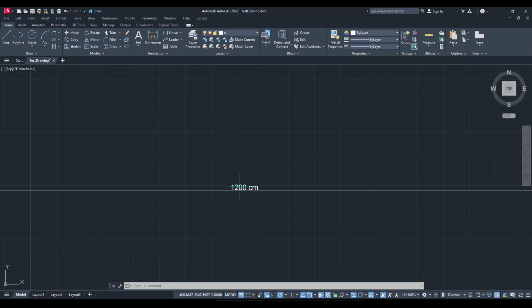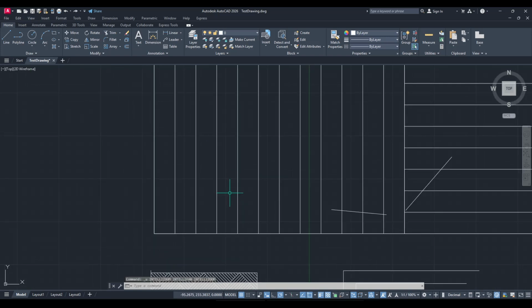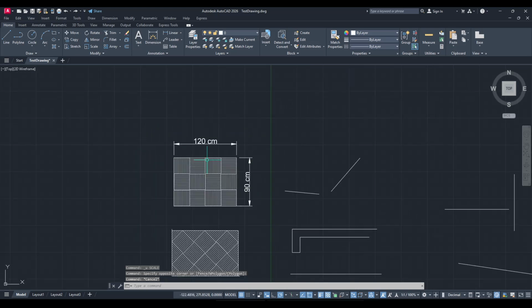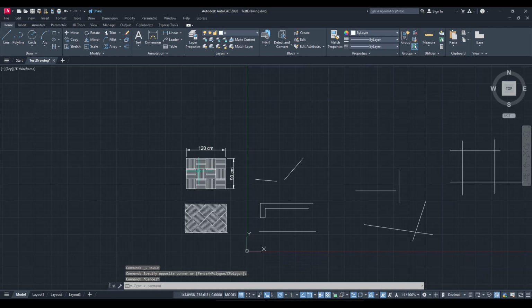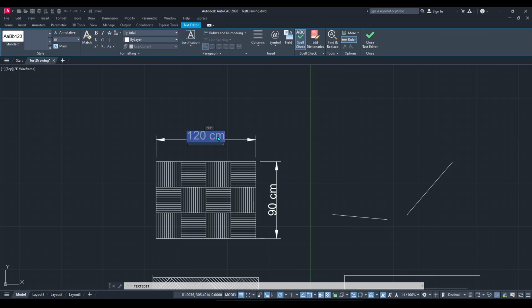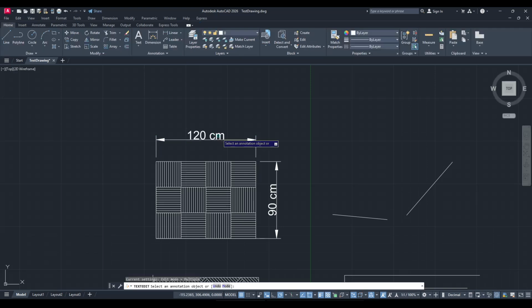properly with that system. A quick best practice is to decide on your unit system at the start of a project and set it with the units command before you begin modeling. That prevents mismatches later. If you're working with files from different sources, check the units first. Set your insertion scale to meters, and then bring in external content so everything remains consistent.